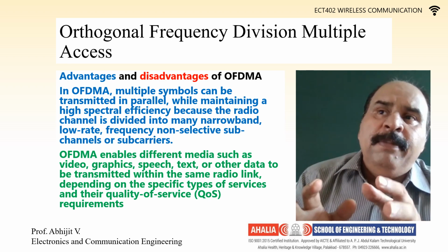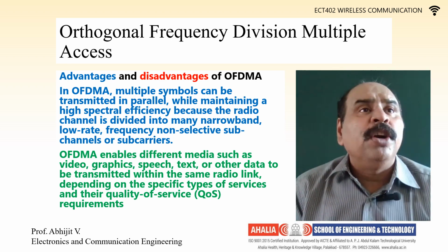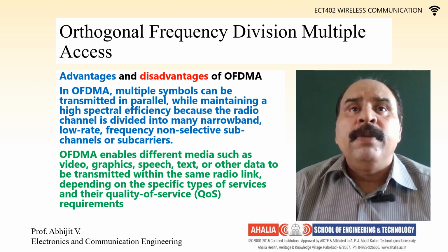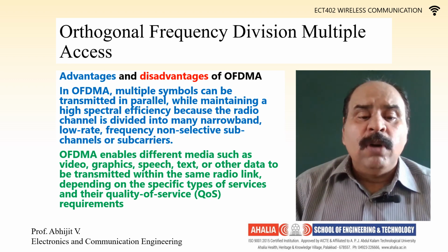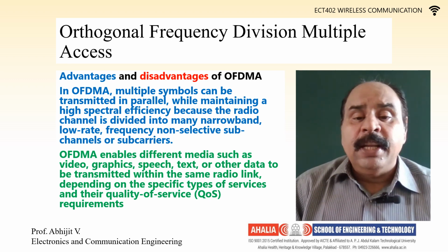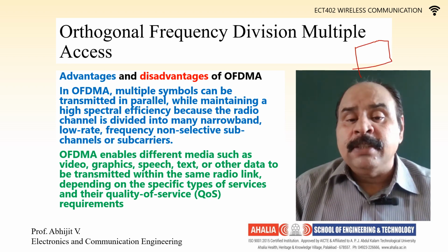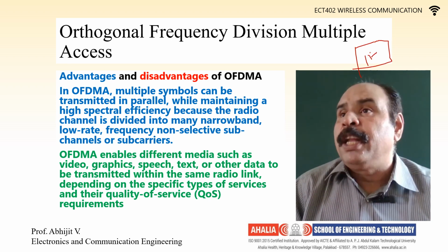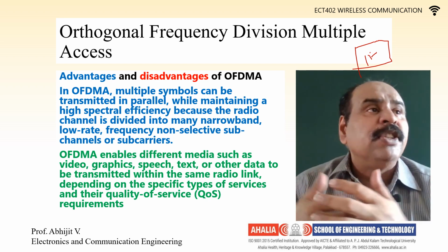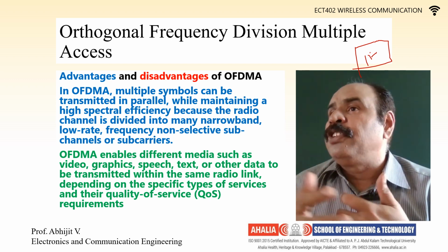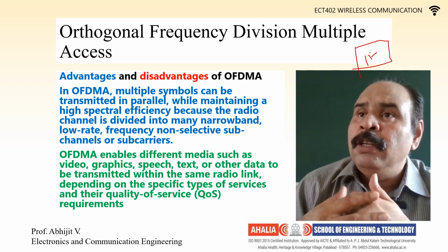We are not seeing OFDMA in detail here because OFDMA is nothing but OFDM. You know OFDM, what you are doing? How many of you remember OFDM? In OFDM, in a multi-carrier system, we have what is called the IFFT, right? We are taking the transform of the signal that has to be transmitted, and we are generating multiple orthogonal signals to be transmitted over the same channel bandwidth. Am I right? Yes or no?